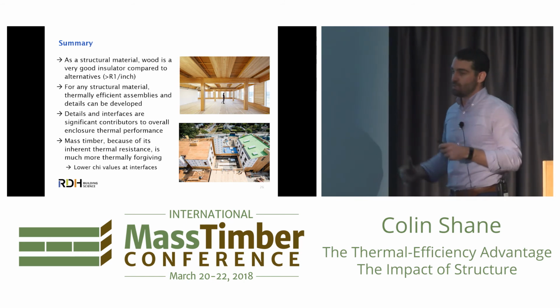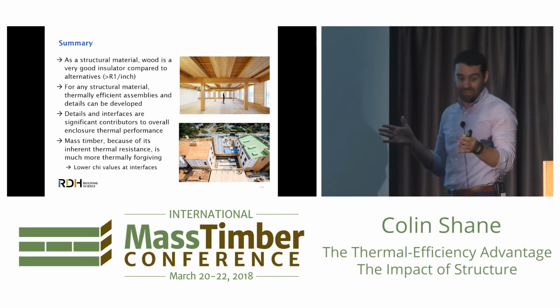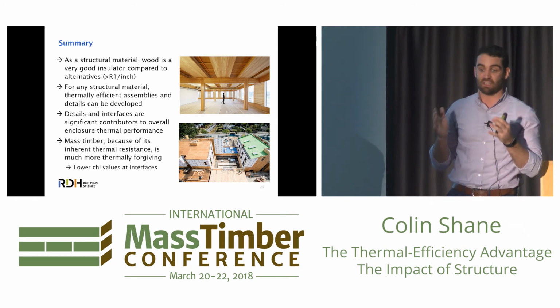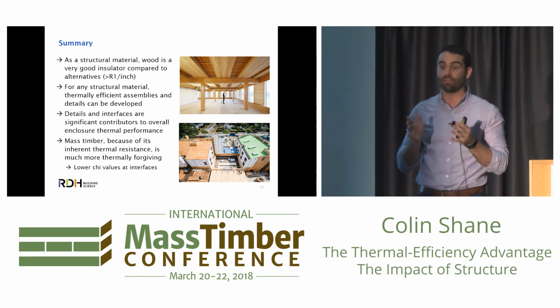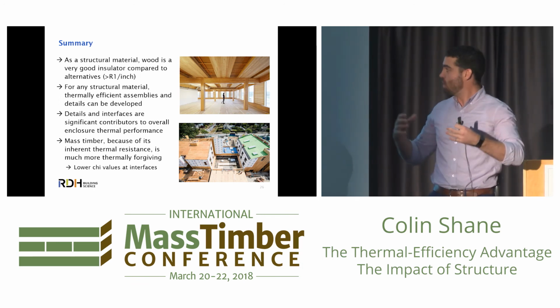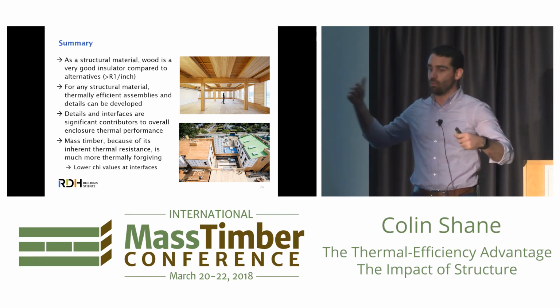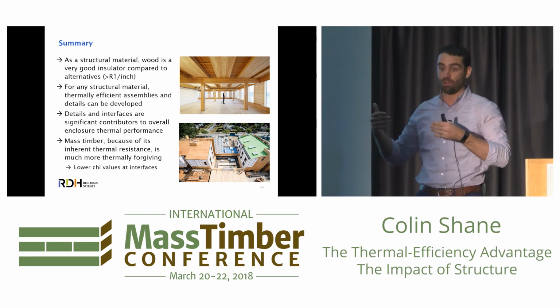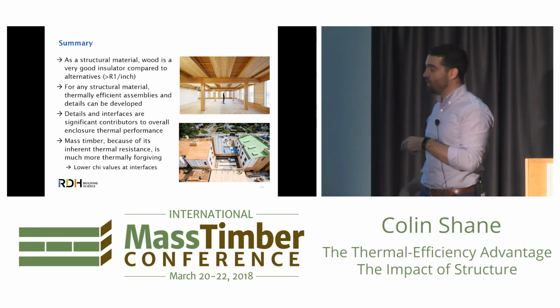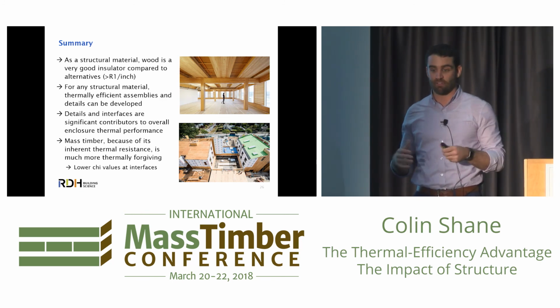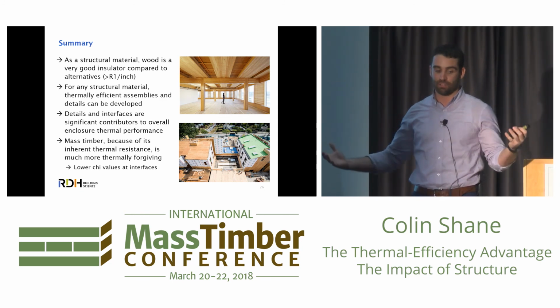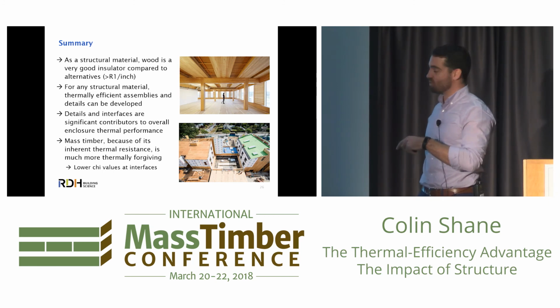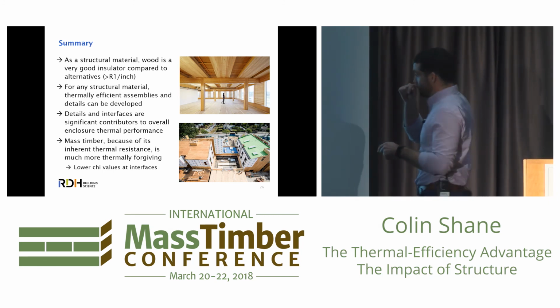So not only it may thin down the amount of insulation we need on the exterior of our structures to get equivalent R values in the center of the wall, when we get to interface details, window perimeters, parapets, exposed floor lines, things like that, really significant savings there from overall heat loss and overall energy usage of our buildings as a result of that insulative structural material.